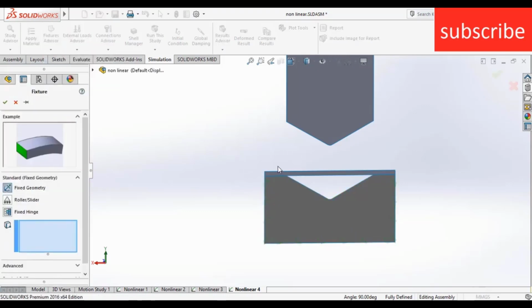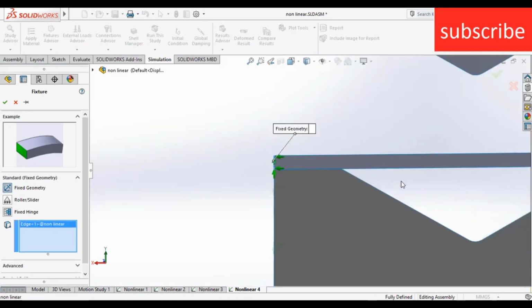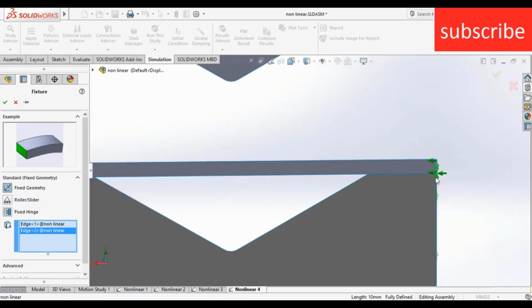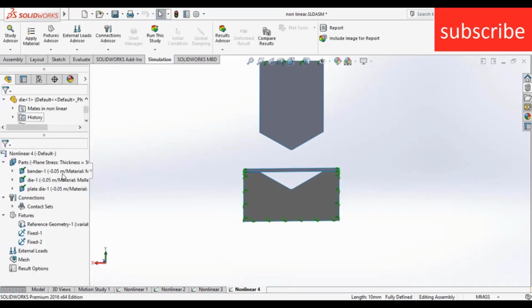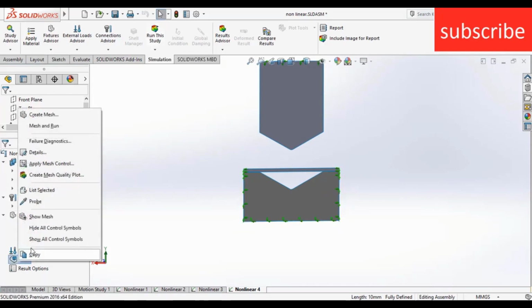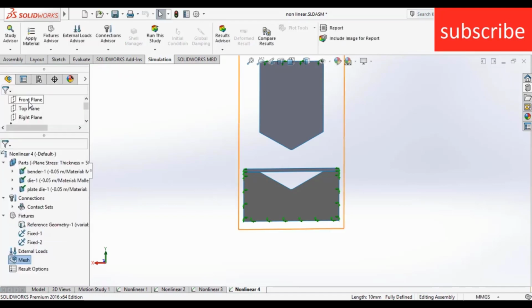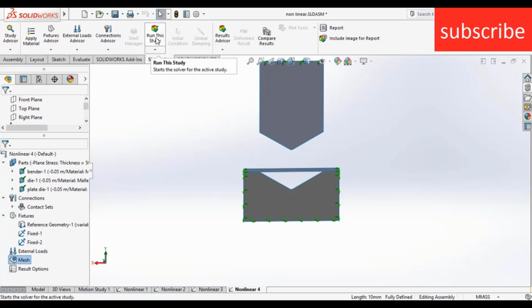Again, click on fixed geometry, select this side of the plate so that when the plate gonna bend, these edges don't move. Click OK. After that, just click on run this study, or you can right click, apply mesh, or you can create the meshing as per your requirement. Here I just simply want to show you how to do simulation. I'm not going into details.